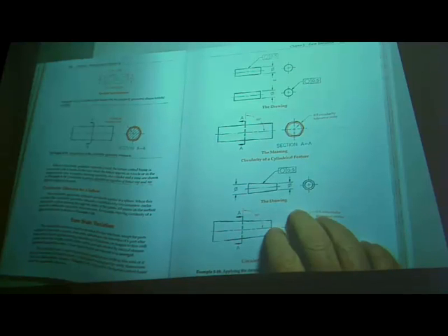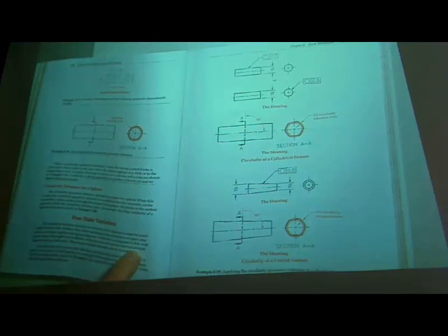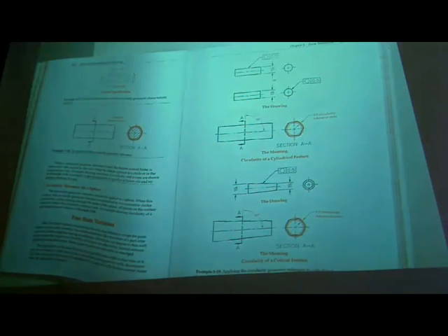Then there's the free state variation. Again, I kind of touched on that earlier. Distortion can happen to thin wall parts where the weight and flexibility of the part are affected by internal stresses applied during fabrication. If they're real thin parts, it could even be metal, not necessarily rubber. If it's an extremely thin, tiny part, it might heat up during manufacture, and then when it cools, it could change shape.